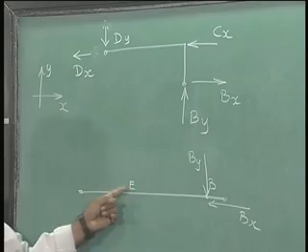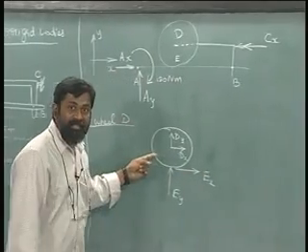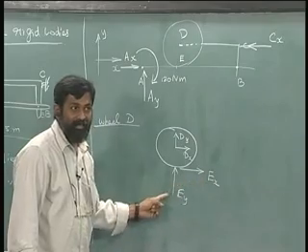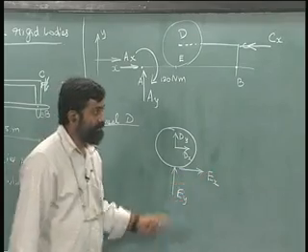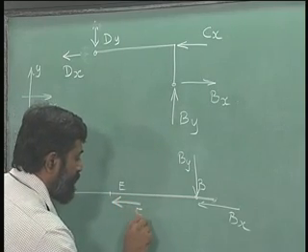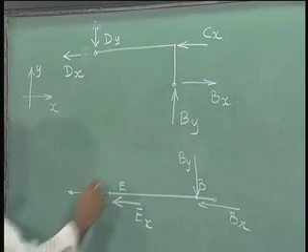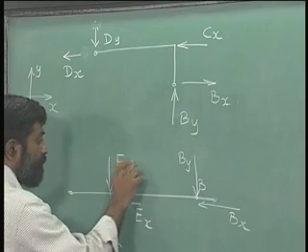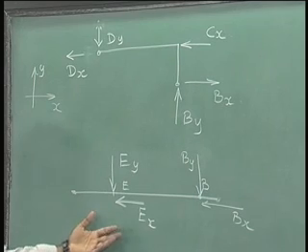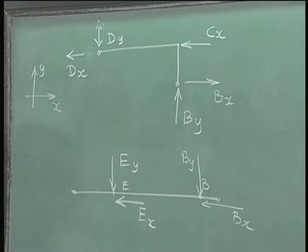At E there is an interaction with the wheel, and therefore I should take the opposite signs of this Ex and Ey and insert those as the forces. So Ex and Ey. This way we can avoid adding more unknowns, we take equal and opposite reactions automatically.